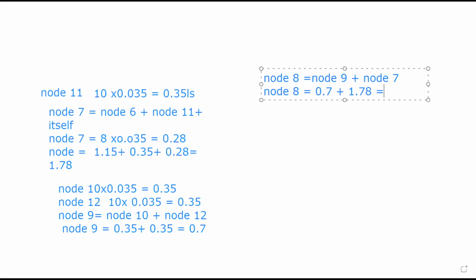So one thing you must see is that as you are going upstream, the pipe size is increasing, the demand is increasing, but as you're going downstream, the demand is reducing. That's why you don't use one type of pipe. As your pipe is coming in from the storage tank, it's reducing. Just to check in your house, from the storage tank, you use 2 inches pipe or 1.5 inches pipe. As it's going inside the house, you start using 1/2 inches, 3/4, and what have you.